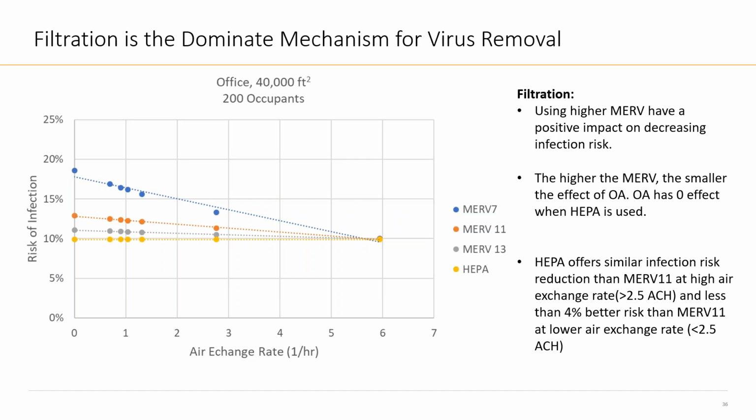Okay, and last one here. Can demand control be used in combination with the indoor air quality procedure? So just to answer, in principle, these are two different procedures, and it will not make sense to do both of them, because with the indoor air quality procedure, if you use an air cleaning solution that can remove both the pollutant generated from humans and the pollutant generated from the area, you don't need the demand control ventilation anymore. It will just add cost and more controls, etc.